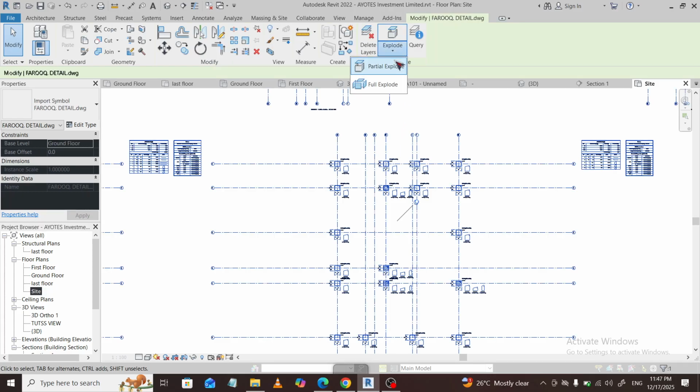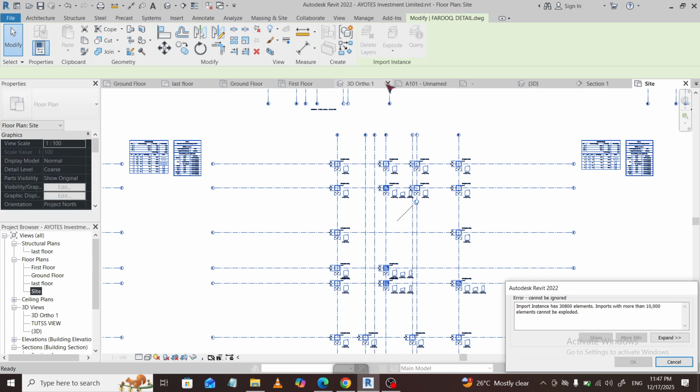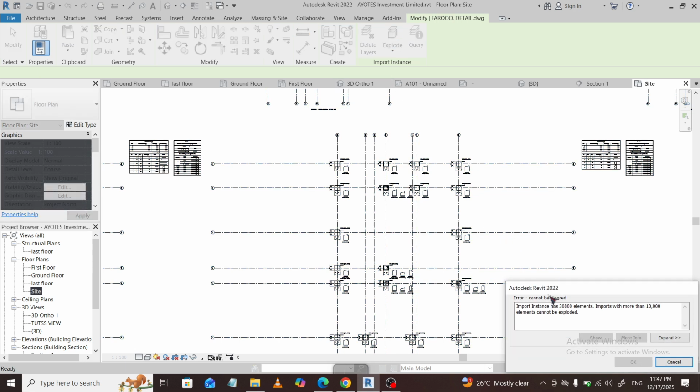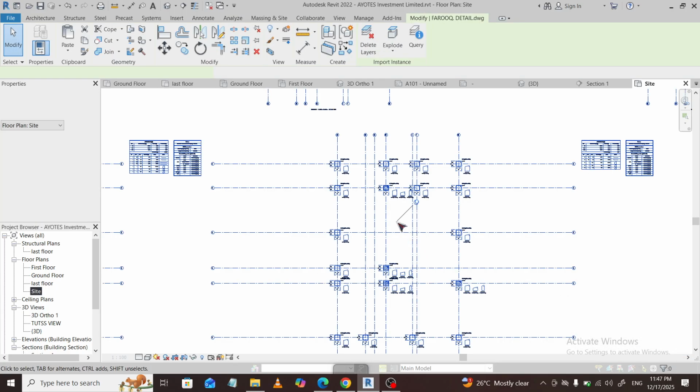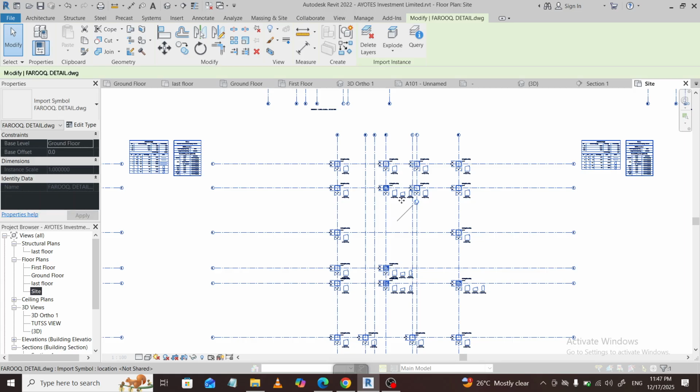After the explode, take a moment to clean up the resulting line work. It's normal to see hundreds of small segments, overlapping lines, and filled regions. Start by selecting large areas and using the filter tool to isolate detail lines, text, or filled regions so you can manage each type efficiently. Delete what you don't need, especially duplicate or stray segments. Use Trim and Extend to Square to tidy up corners, and join where it helps reduce fragmentation.